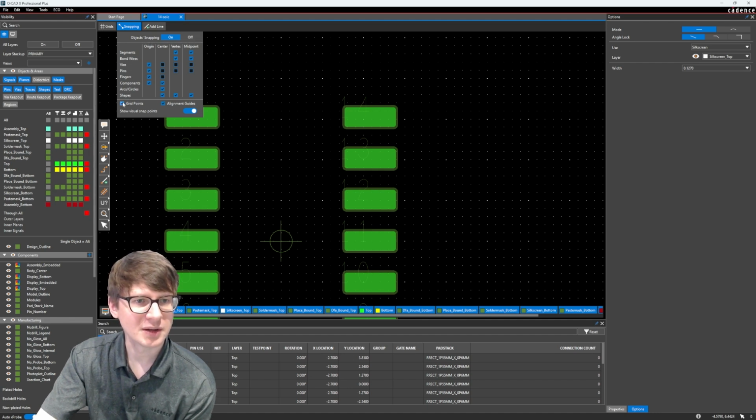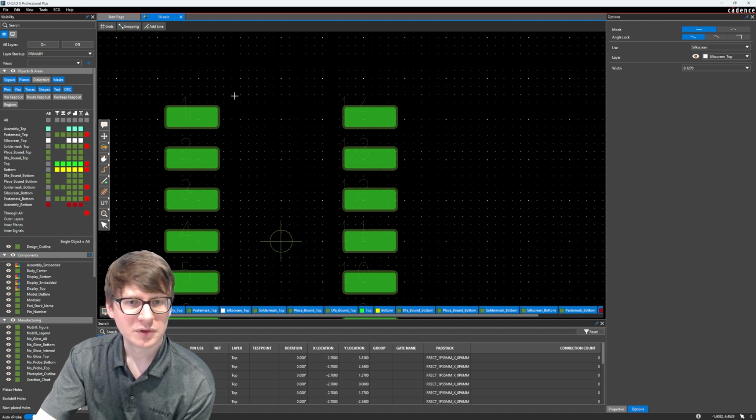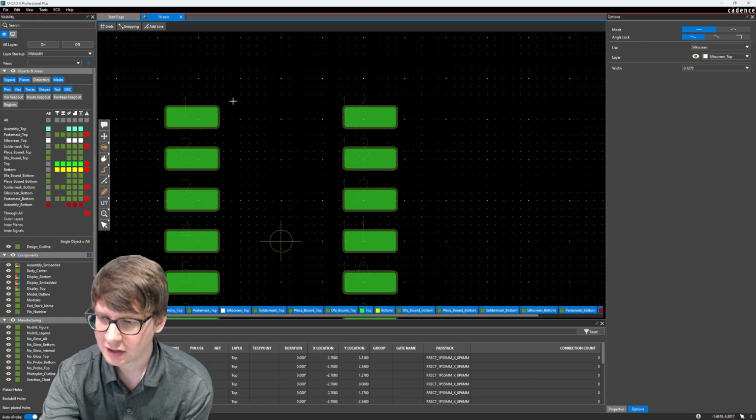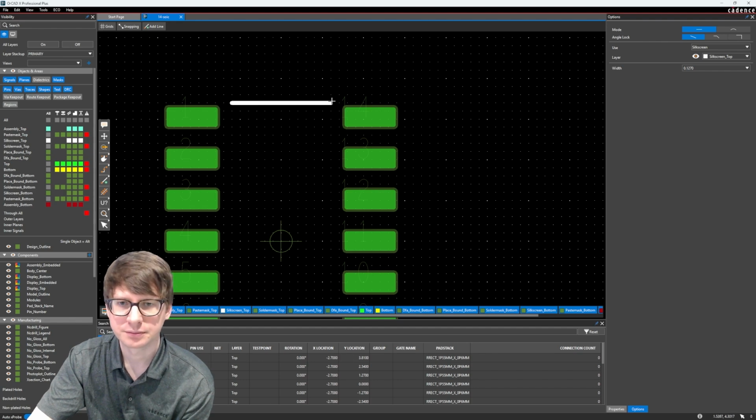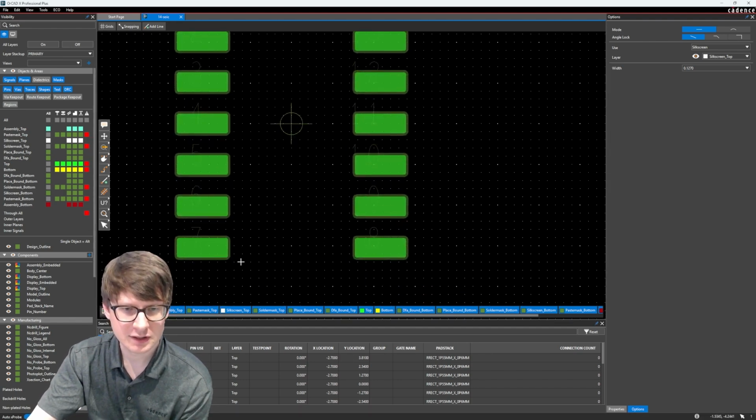Oh, that's for object snapping. Yeah, so we are snapping to grid points. So if I hover over this point, even if it says in the bottom right 4.3017, it'll snap to 4.3. And then we can draw that straight line. And same thing on this side, negative 4.3, we can draw a line, which would be this one right here.